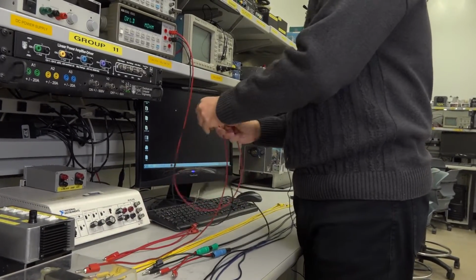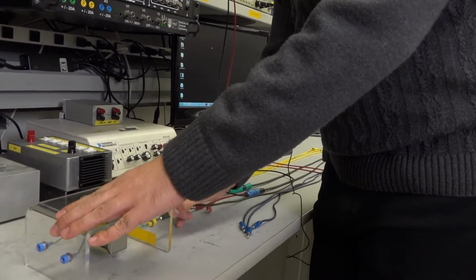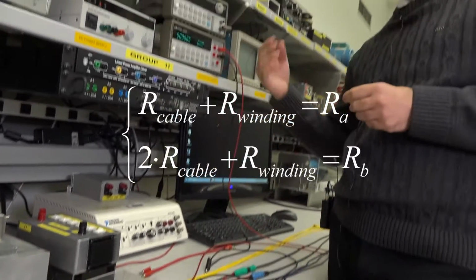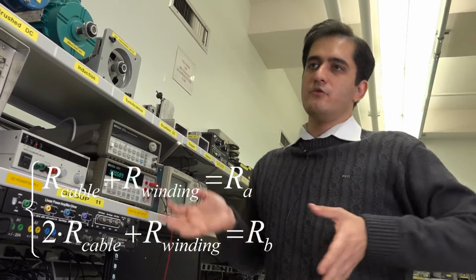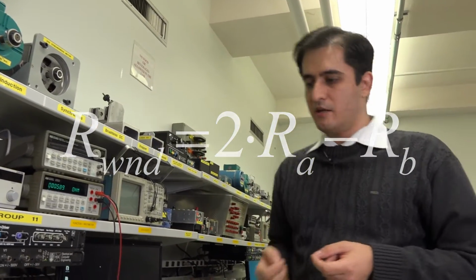This will allow us to have two different equations for two different resistance measurements, but we're going to have two unknowns. So we're constructing a two-unknown, two-equation system, and then we can calculate the exact resistance in this transformer by using this technique.